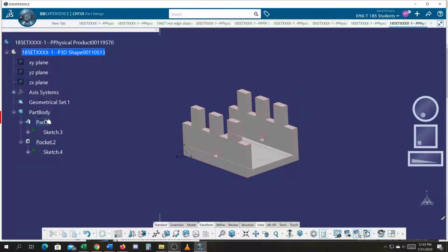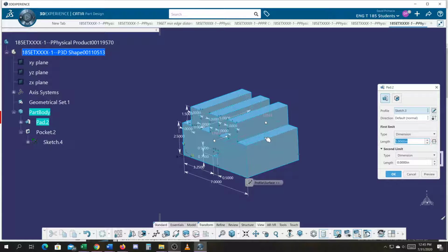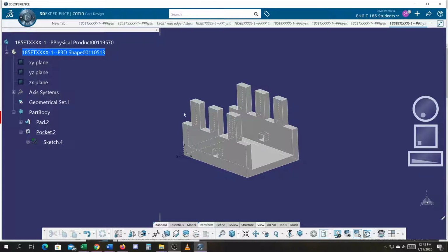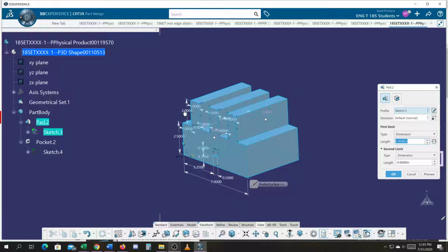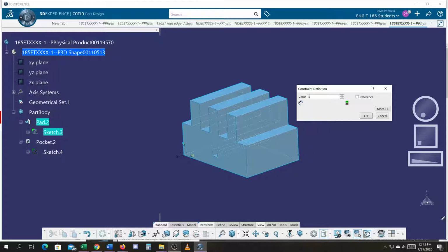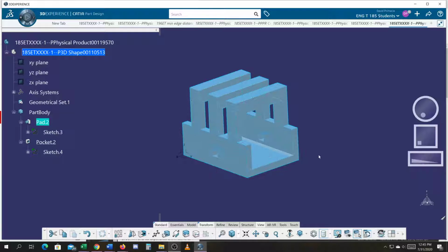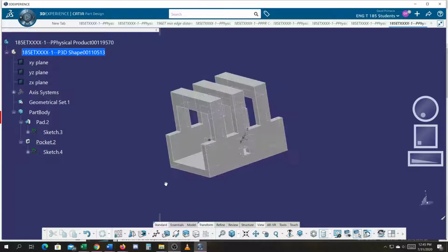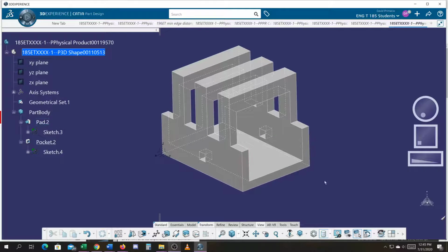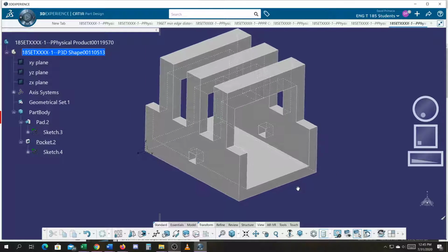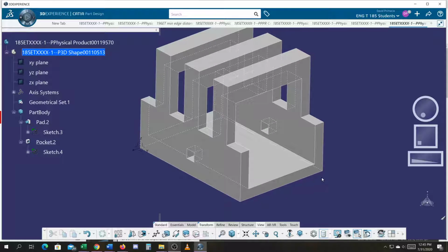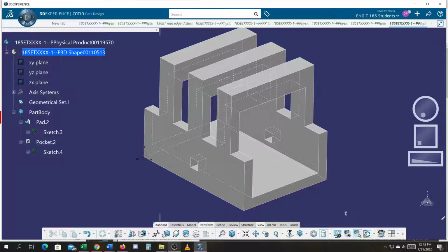even if I were to change that pad to full, this dimension here to 2, select OK, still going to trim it off. Again, the problem is if you go to this sketch and I change that sketch to 3, now I got the handle that's going to come in again up on the top, which is cool again if that's what you were trying to create. Just for fun, you guys can do it. But if you take the 196 class, we're going to show you things on how to link stuff up so this doesn't happen if that's not your intent.